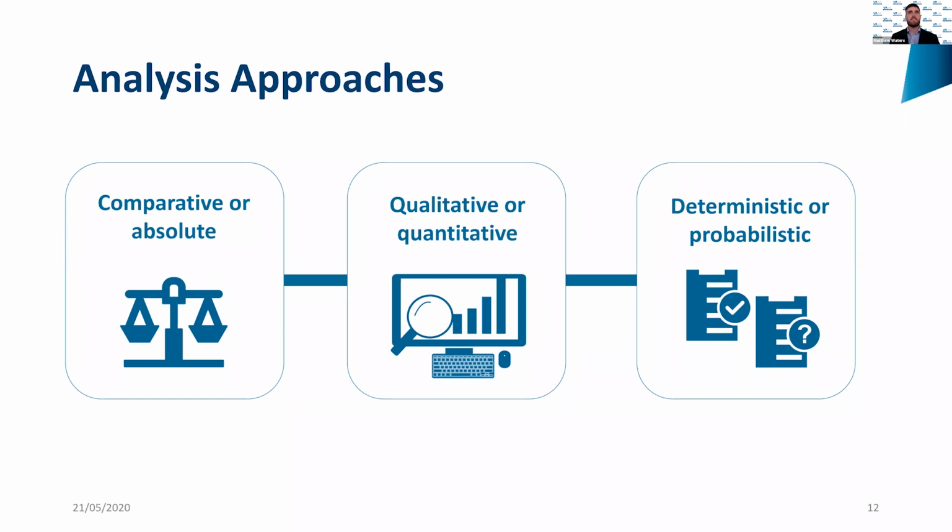We've also talked about qualitative and quantitative approaches or methods of writing in terms of the performance requirements and how they're written. So qualitative is one that involves non-numerical and conceptual evaluation, and quantitative, we're looking at numerical evaluation. There's deterministic and probabilistic approaches as well, and deterministic is based on physical relationships, which is derived from scientific theories, and this will produce the same outcome, but it won't give you a probability of that outcome being realised. So a common example of that used in fire engineering for travel distances is something like ASET, RSET analysis.